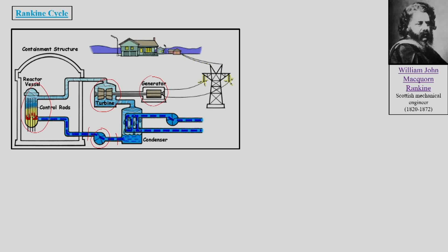where it comes close to the saturation steam point. Then this cycle being a closed cycle, it needs the same amount of liquid water again at the intake. So we have a condenser here, and that condenser condenses the complete steam into liquid water, and then this liquid water is again passed to the pump.